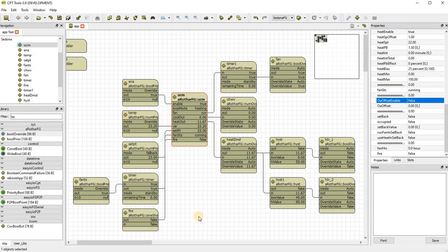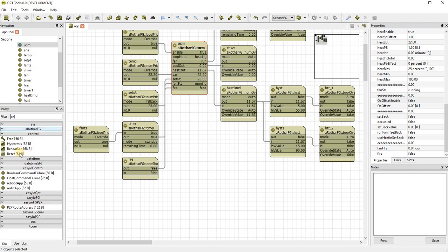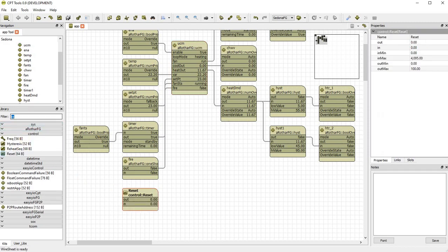Some specifications call for energy management or energy control on degree days where the outside air temperature is outside the design conditions of the unit. So you're able to offset the set point based on that. So let's get a reset. Let's get a temperature.